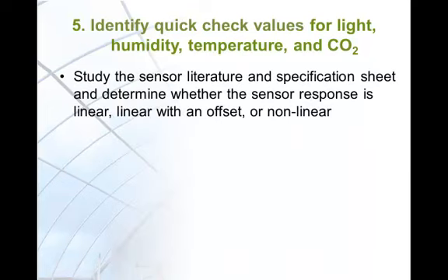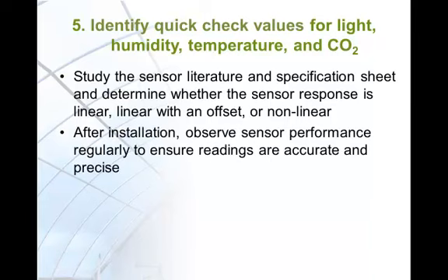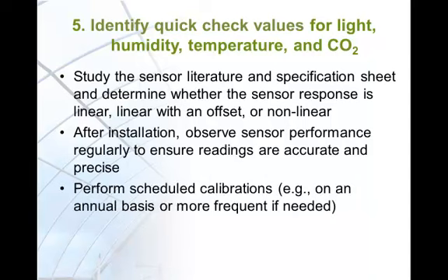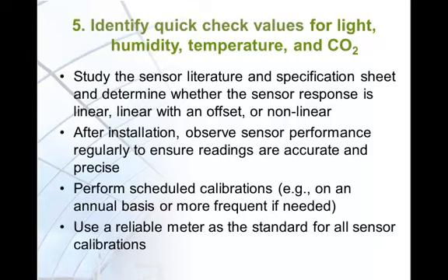As a sensor user, you should study the sensor literature and specification sheet and determine whether the sensor response is linear, linear with an offset, or nonlinear. After installation, observe sensor performance regularly to ensure that readings are accurate and precise. Perform scheduled calibrations on an annual basis or more frequently if needed. Use a reliable meter as the standard for all calibrations.